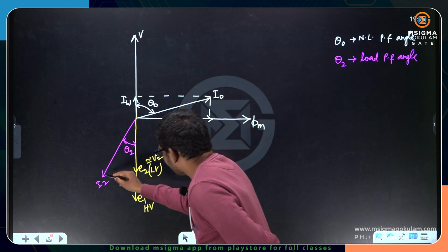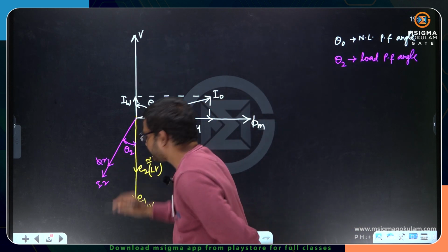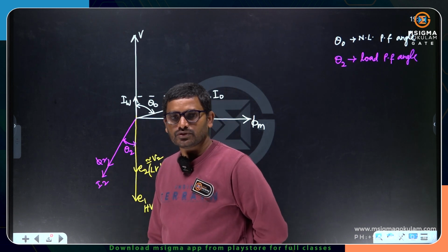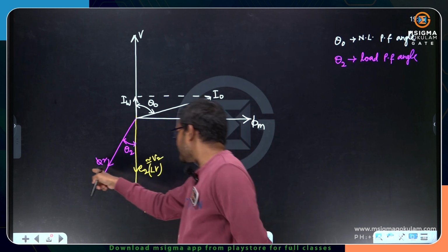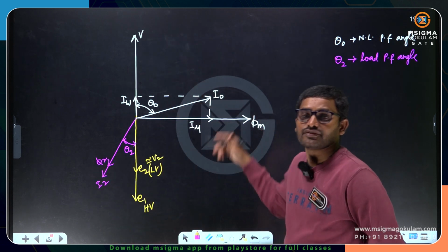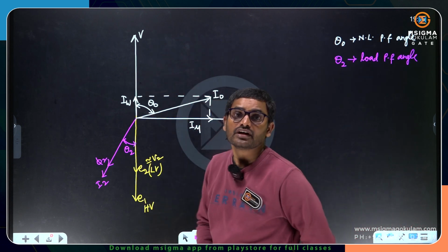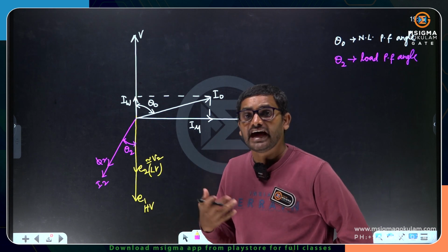If I2 is lagging like this, in the same phase you will have phi 2. Because whenever I2 is circulated in N2, you will get magnetomotive force, and flux phi 2 is established. Now this phi 2 is going to oppose phi m. Therefore the net flux comes down, the EMF comes down, and the potential difference increases. Therefore one more current flows. The source will drive one more current. What is that current? I1 dash.